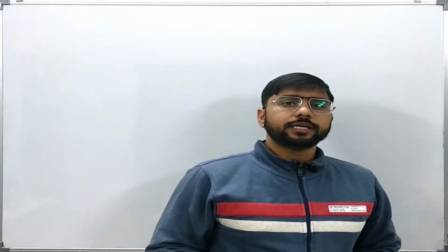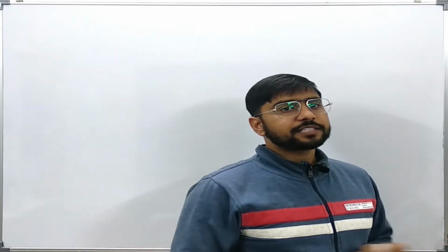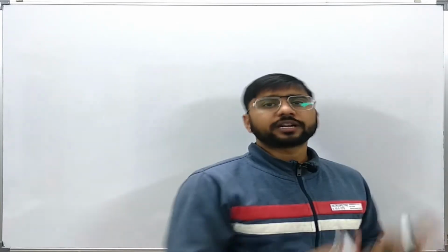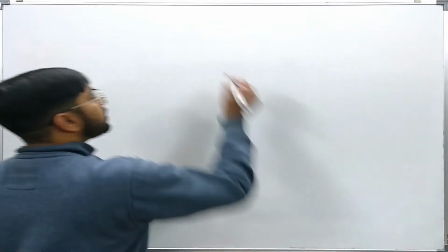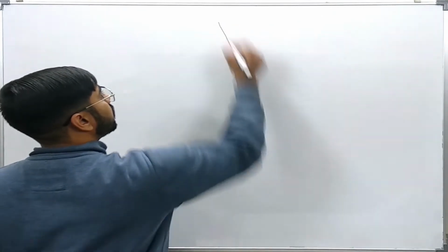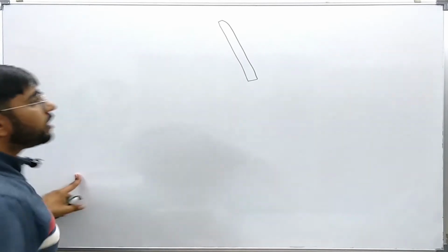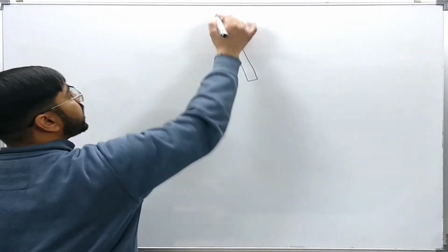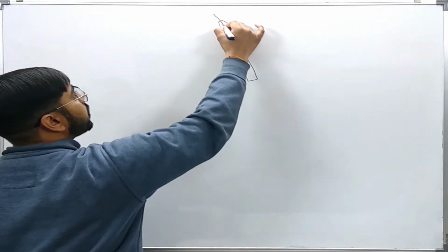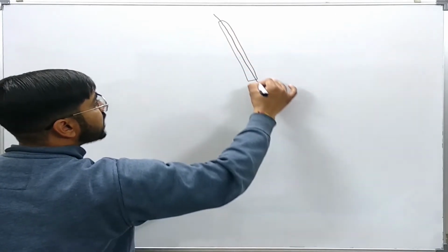Usually CTs can have multiple kinds of design. One of the designs is having the CT in the bushing of the transformer. Let us say this is the HV bushing of the transformer. This is the insulated medium, and the HV conductor is passing inside it.